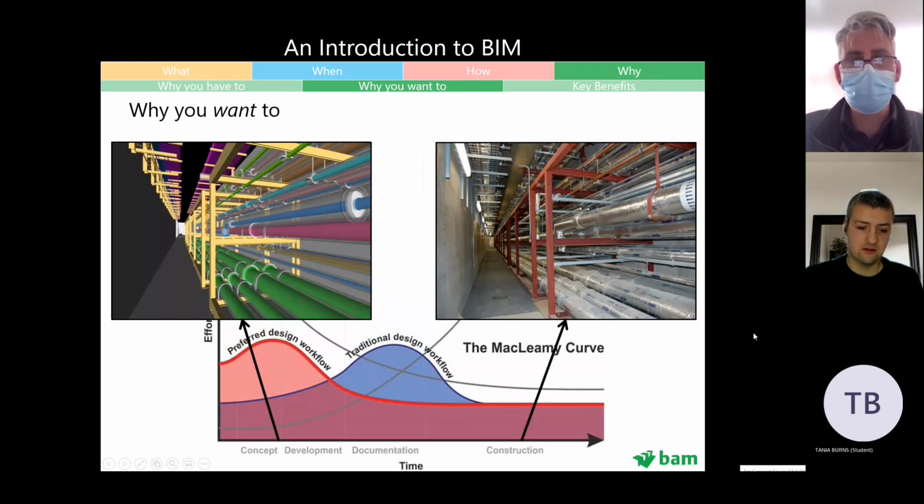So that's really where BIM comes in. If you're able to produce a coordinated model really early on, then you're saving a lot of money, and what you designed at this stage is what's eventually built, and you've de-risked significantly because you've already checked that everything fits, everything's coordinated, we don't have clashes, we don't have ducts and pipes running where we already have steel installed, so you have to divert it. The cost of that kind of thing builds up.